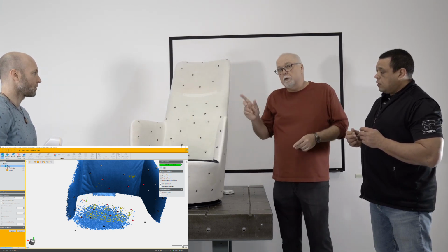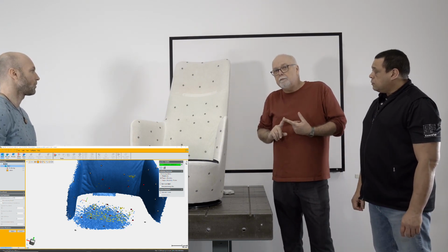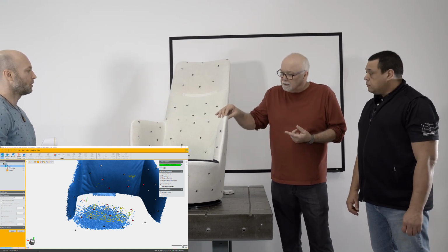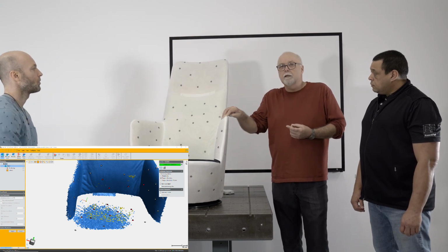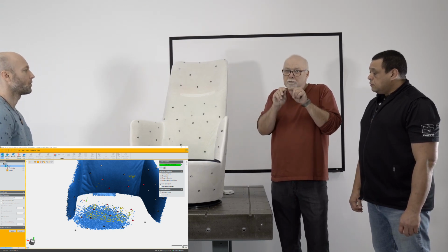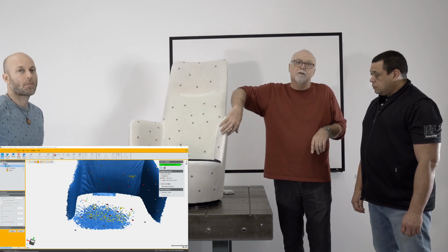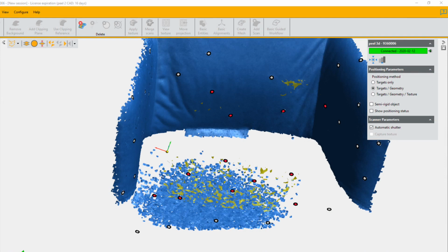And as I said when we were unboxing, there is a box of very sticky targets, there's a box of ordinary sticky targets. On something like this, which is loose, felty, you should probably use the high stick targets so that they don't pop off. And try not to put them on high radius curves because that will make them pop off. Yeah. Okay. I'm just going to scan the target surface.